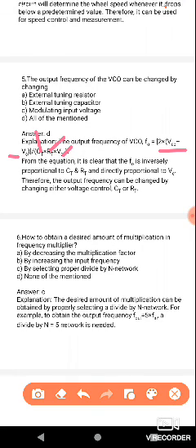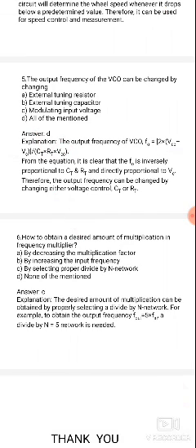From the above equation, it is clear that F0 is directly proportional to VC, the control voltage, and inversely proportional to the external resistor RT and external capacitor CT. Therefore the output frequency can be changed by changing either the control voltage, CT, or RT.